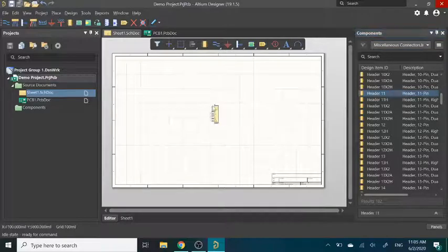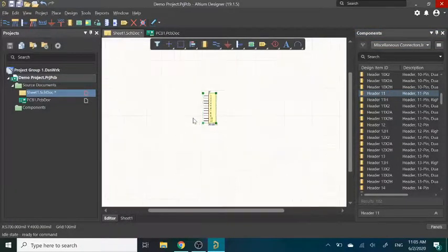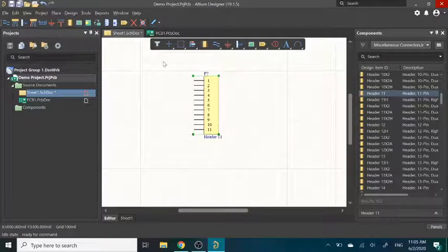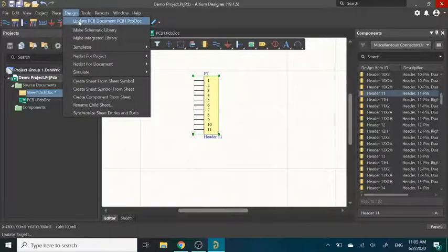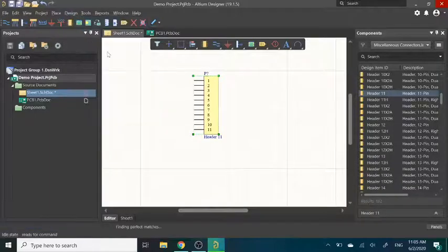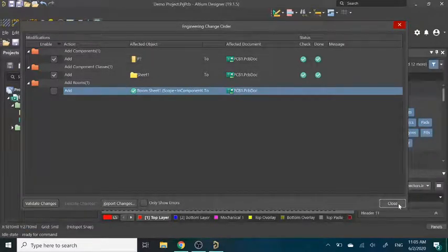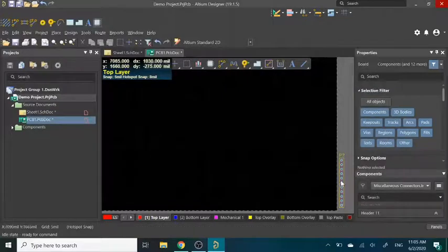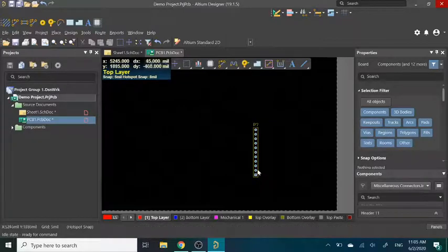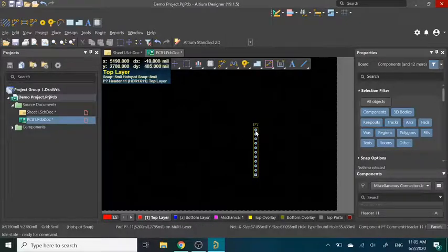Every component has the schematic diagram, which is this, the schematic symbol, which just shows the pins, and the footprint that shows up on the PCB itself. Close this. So there's the footprint right here. It doesn't matter what the schematic looks like, but this part has to be correct or else your part will not fit.